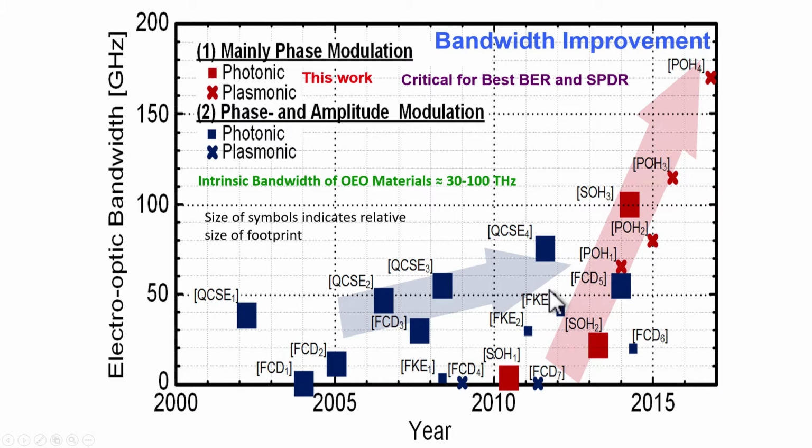Okay, this actually gives you a comparison of technologies. We mentioned lithium niobate, but that isn't actually a very good comparison with modern state-of-the-art, because lithium niobate has a relatively low electro-optic activity of roughly 32 picometers per volt, and the processing of that makes it very difficult to integrate with modern hybrid integration techniques and achieve these micrometer scale devices.